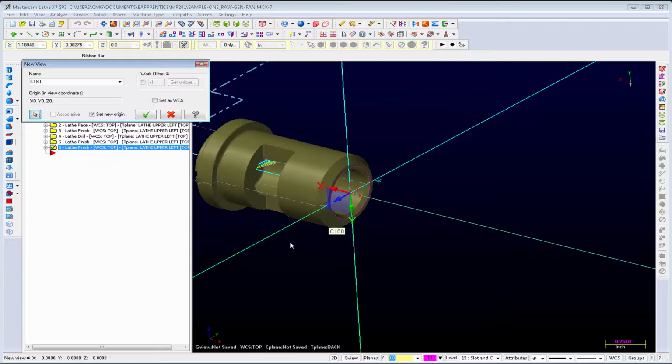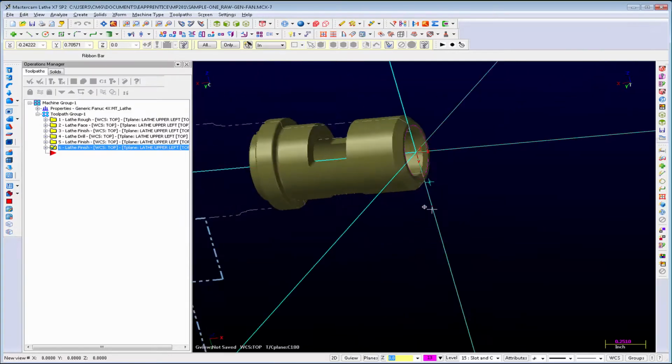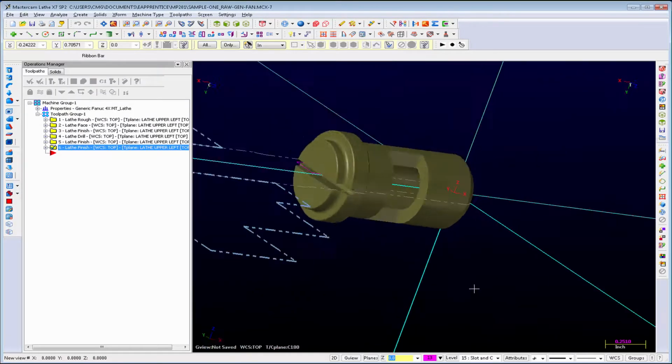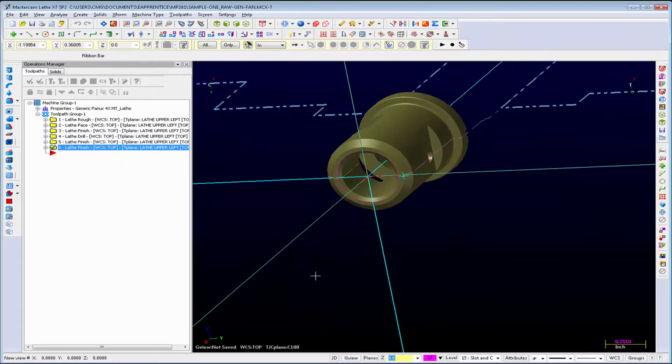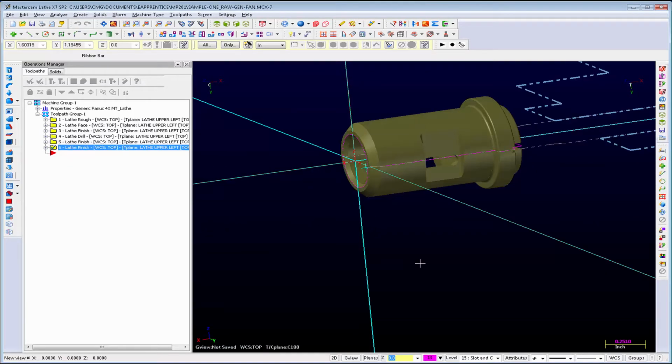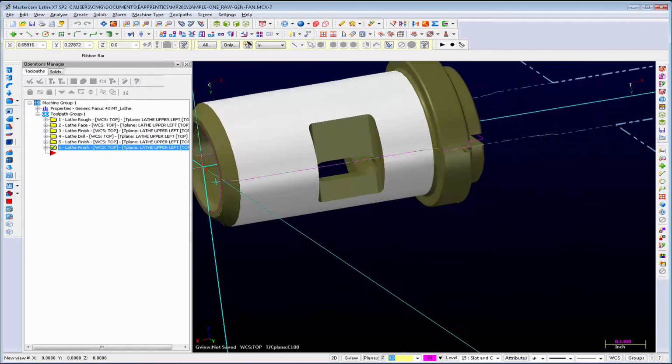Okay? And I will typically do this on a part before I start programming, if it's practical. You know, if you can, go in and set up your planes beforehand. Again, if you use those C-axis toolpaths, it's not that big a deal. So let's do some regular milling, and then let's see C-axis and see kind of what the differences are.